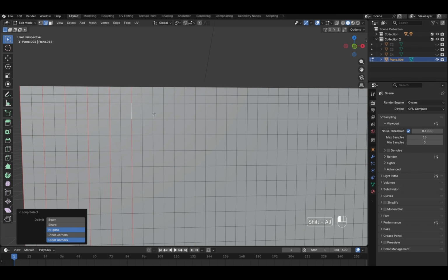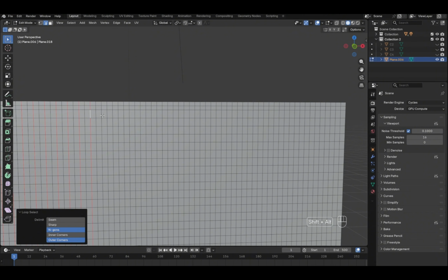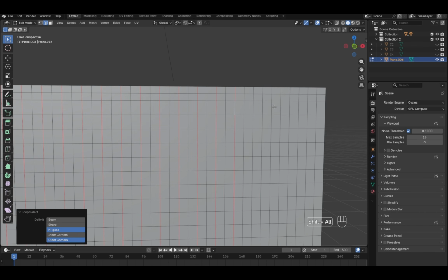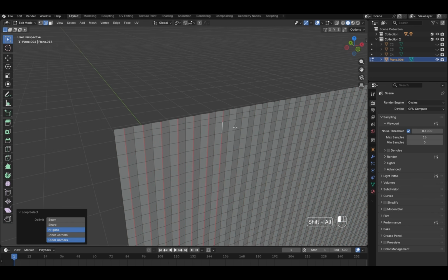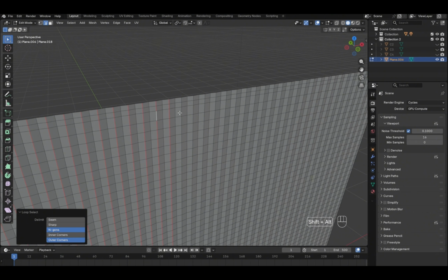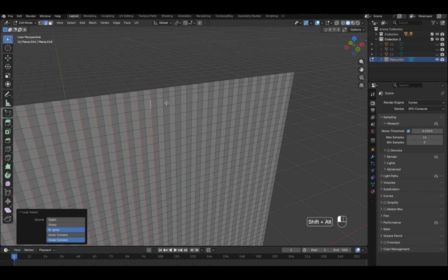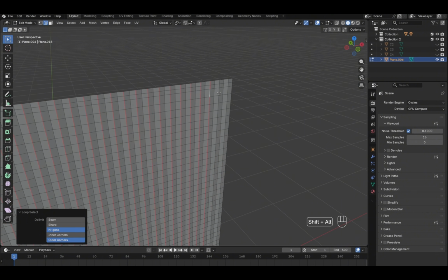Then select every other horizontal edge loop and move them by 0.005 away from the center. Select the neighboring edge loops and do the same thing but in the opposite direction. You can also skip these steps or experiment with different starting geometry.